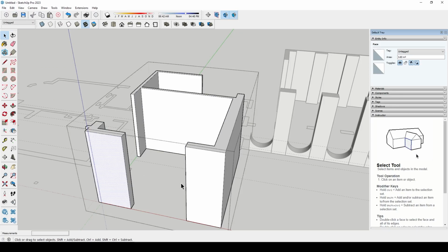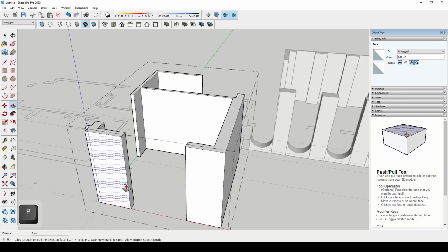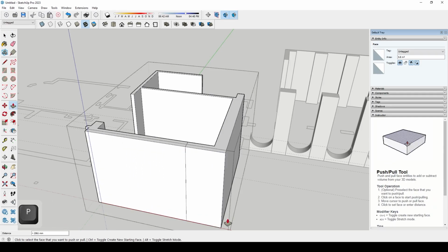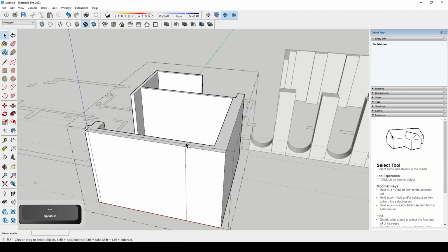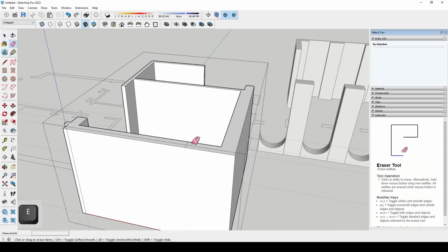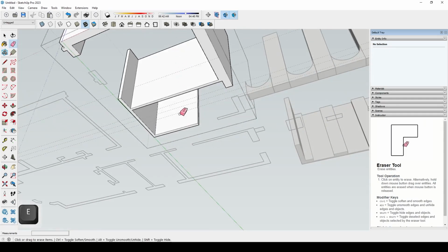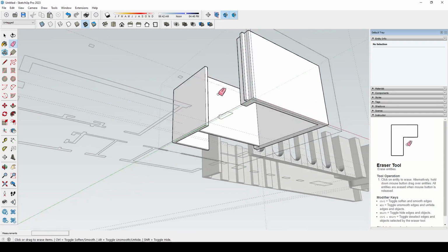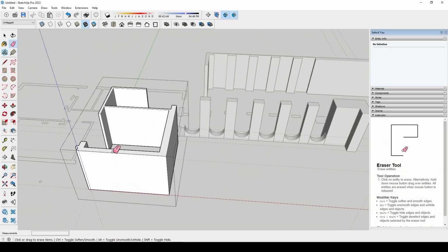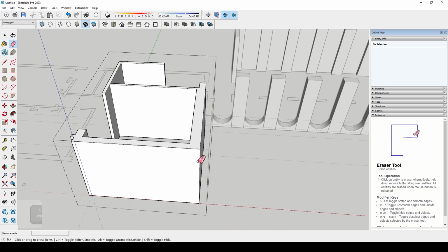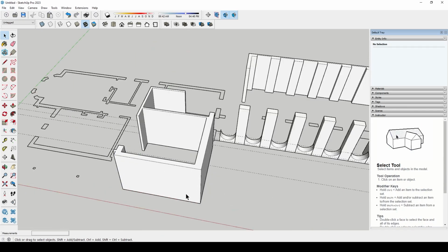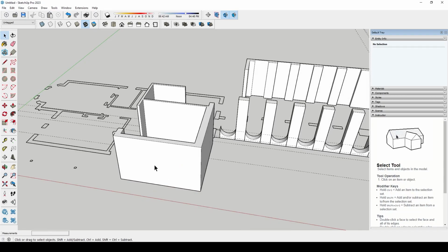I can then go ahead and pull this face that we have over here over to this one, and voila, I can see that that is now a softened line. So I can go through here, grab each one of these around underneath and go over the other side. Perfect. So now this is all part of one wall, and I can go ahead and cut that window out from where it belongs. What we need to do first, however, is make our guidelines so that we know where the window is going to go.